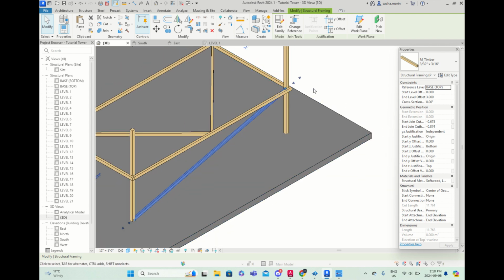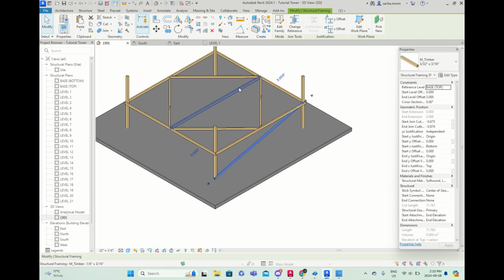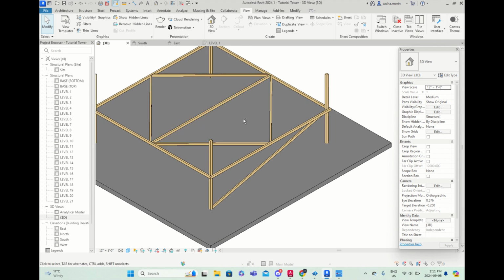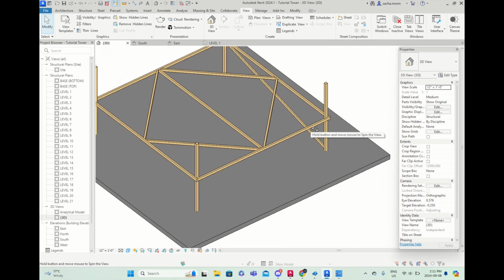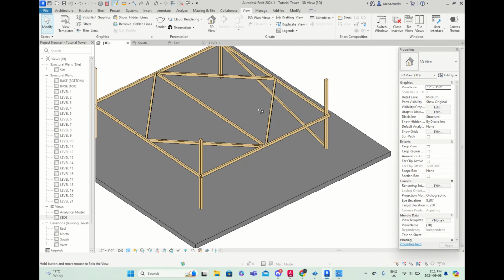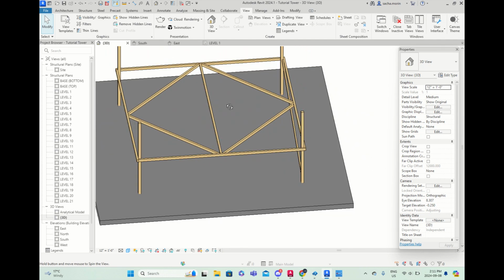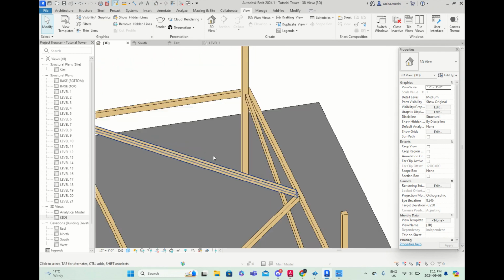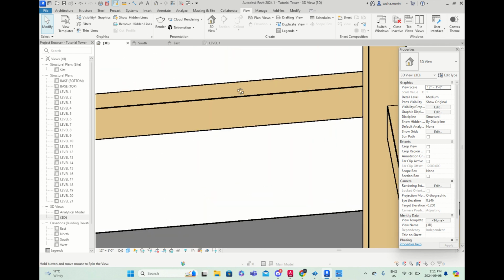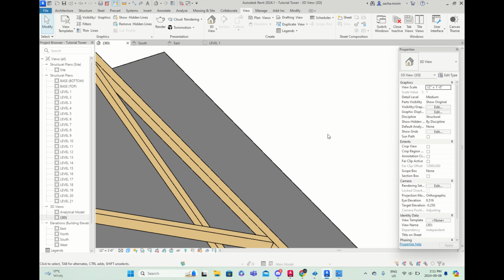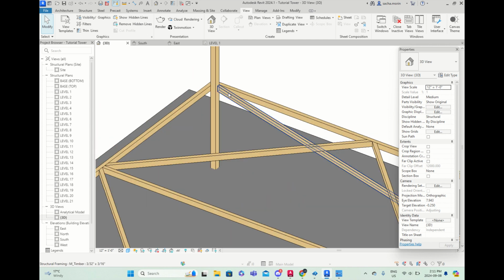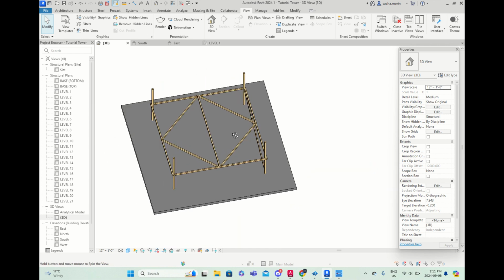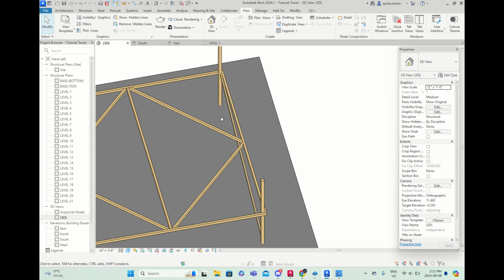So to be able to rotate around your 3D view, you hold down Shift and then right click and drag, and that allows you to rotate around your 3D model. As you can tell, our brace is halfway along the column, exactly as it should be, and it's cut properly. Therefore, we know we did a good job of that. Very nice. So now let's make the other brace.